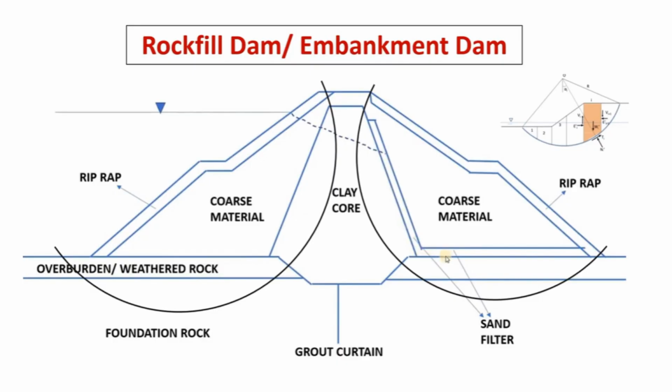As explained already, earthen dam stability is different. Here we have to check the slope stability. For the upstream slope and downstream slope, we have to do separate analysis. The curves indicate slip circles. There are many methods. Each slip circle is divided into many slices to estimate the resisting force and driving force. Accordingly, we can estimate the factor of safety.